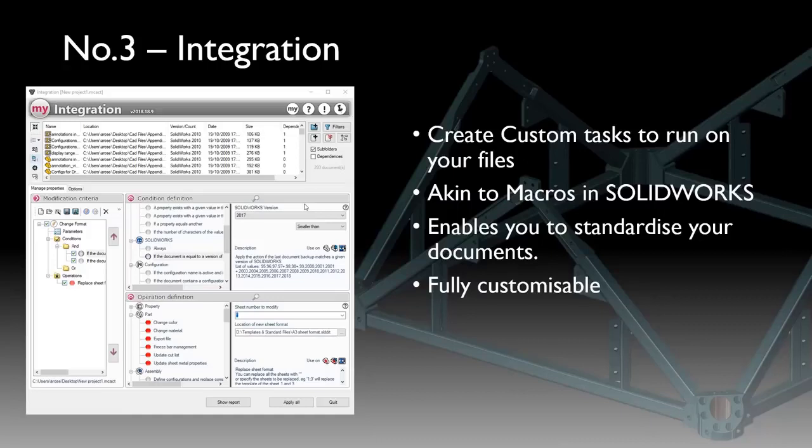The next tool I'd like to pick up on is integration. It allows us to create custom tasks that we can run on a selection of documents, and these are very similar to creating a basic macro. They allow you to run across on a batch of files, and we can use it to standardize our documents inside of SOLIDWORKS. The tool is very customizable, and there's a selection of different conditions and operations that we can then run on our files.